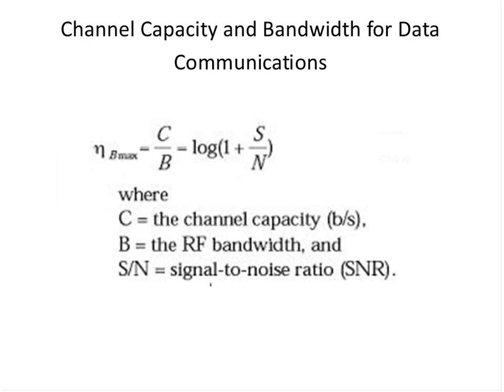It all has to do with the signal-to-noise ratio. For a given bandwidth, you can carry many more bits on fiber than you can on a dirty wire of copper, just because the S/N ratio is much higher in fiber than it is in copper because of the impurities in copper. So the cleaner the copper, the better the S/N, and that's how you saw the evolution in data communication on copper wires.